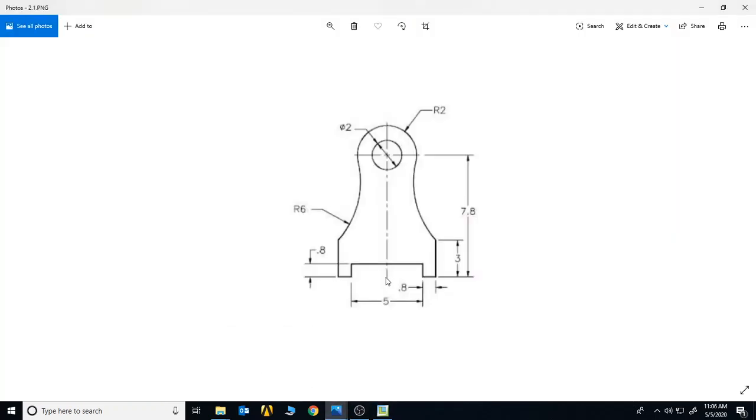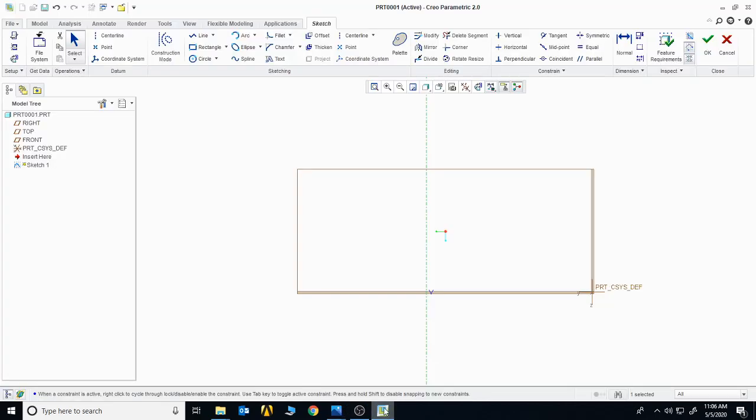Now you need to make only this portion because you will be mirroring it at the end. So from this point to this point, the distance would be 250 because the hole is 500. So we will consider from this point to this point, so that will be 250. Draw a single line of 250 inches. Change the dimensions from 296 to 250. Okay.